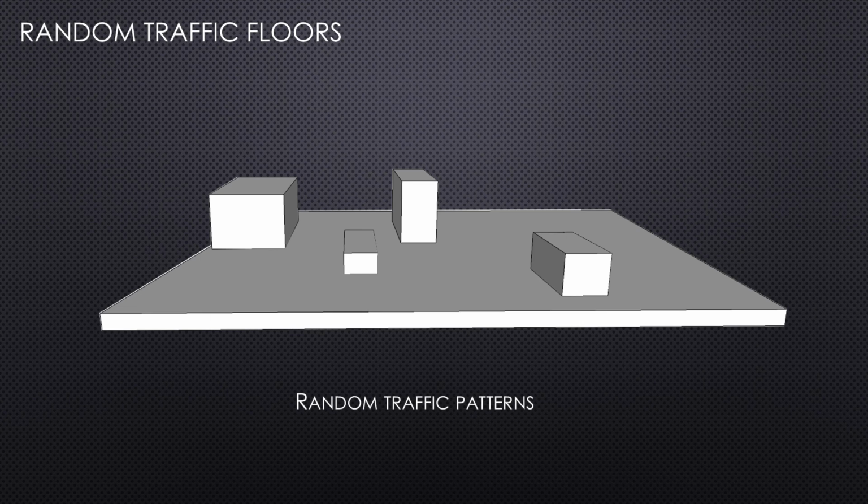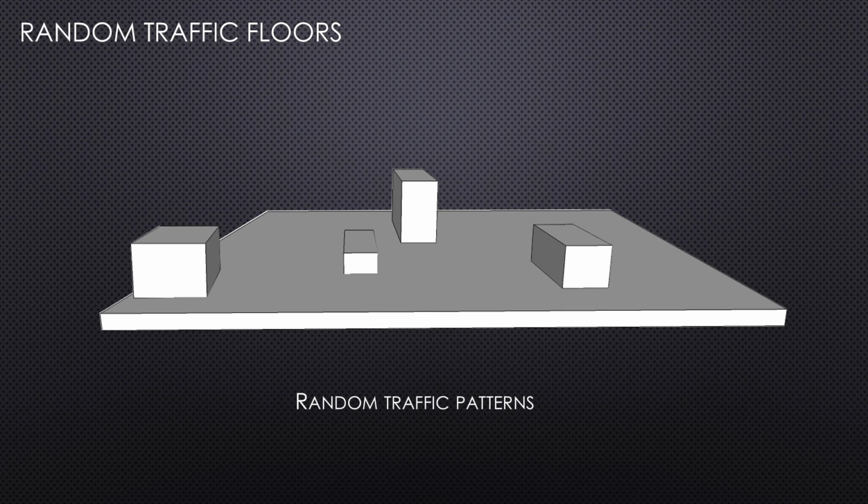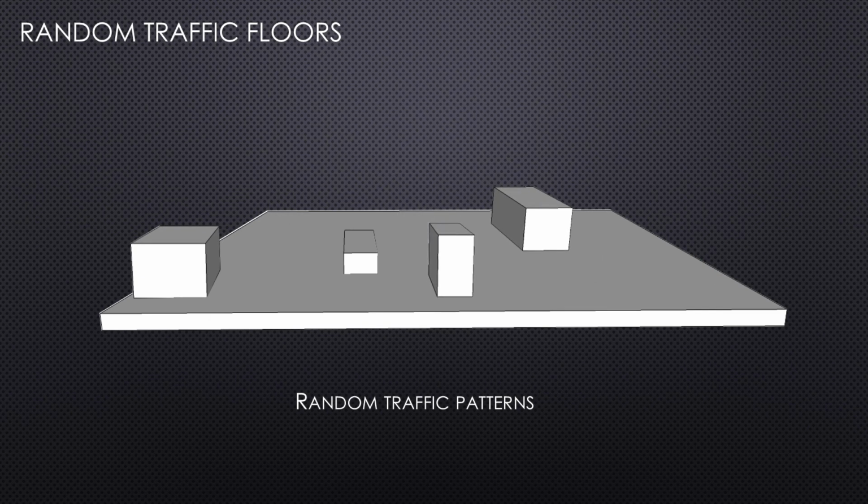Most of the floors placed in the US are random traffic floors. This means that they are designed to accommodate, probably as you might guess, random patterns of vehicle or foot traffic across them. As a side note, this is not to say that defined traffic floors are not flat or level in areas where the vehicles are not traveling. It's common on those same projects to see FF and FL specified in areas where there isn't defined traffic.